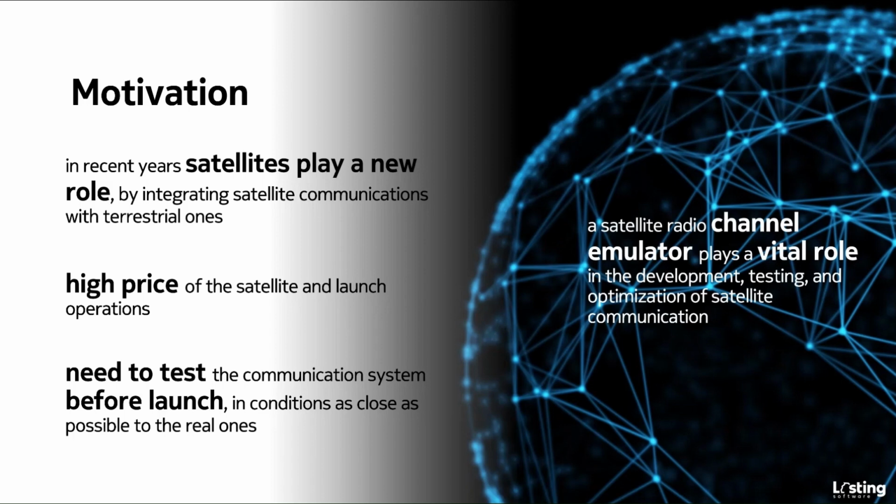Satellite radio signals are subject to various impairments and distortions as they travel through the Earth's atmosphere, including delay, Doppler effect, multipath fading, signal attenuation, interference, and other channel effects. The channel emulator mimics these conditions to simulate the behavior of a satellite communication link accurately.